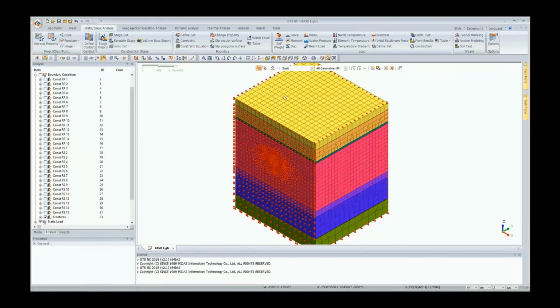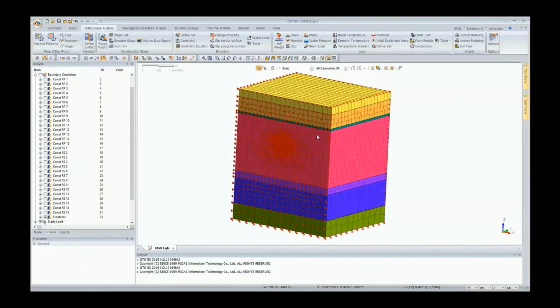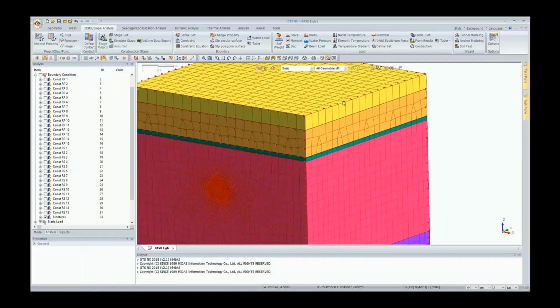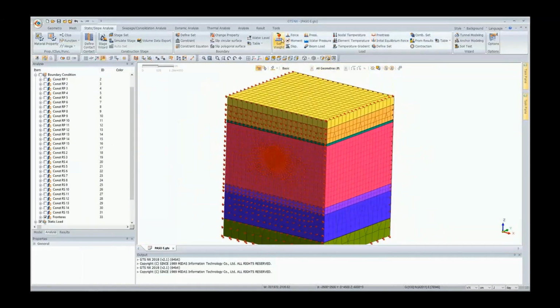So now we see here we have these icons displaying for these boundaries in the y direction, and then in the bottom fixing what would be movement or displacements in x, y, z, which is basically simulating the contact with bedrock. And so it's actually kind of easy to see based on the icons which direction it's fixing the movement for.